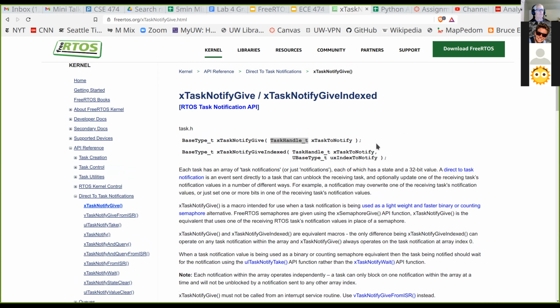actually, I can pull it up. We do not actually get task handles because you have to put a pointer in one of these 2 nulls. I forget which one it is. And you can look that up under xTaskCreate. And it's a pointer to a certain type, which is called a task handle. And that's like the barcode for your task. And so task create returns that task handle to you. Okay, and so you would need to do that.